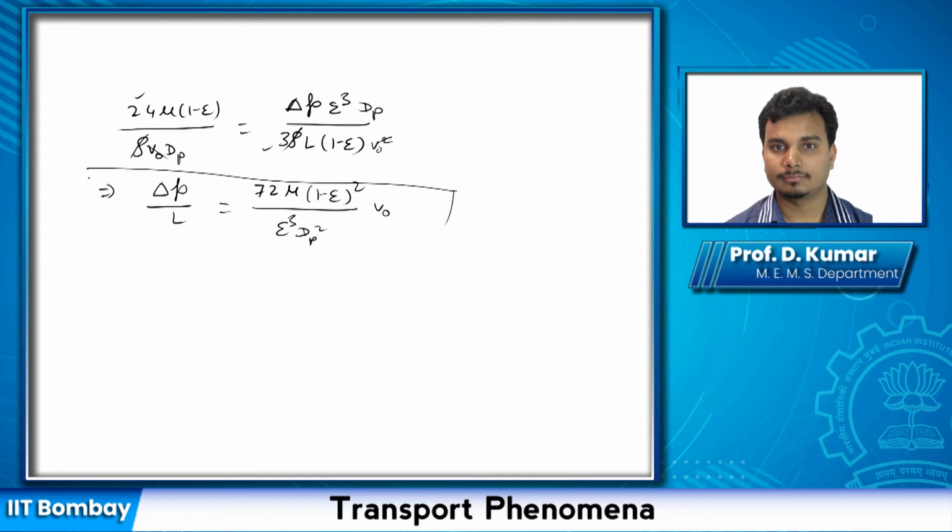What we did was simplify this packed bed and then do this as flow through a single pipe with equivalent diameter. And we have come up with this equation. Based on experiments, this analysis actually gives you very nice, very accurate formal dependence on velocity and porosity and particle size and viscosity, and so on.